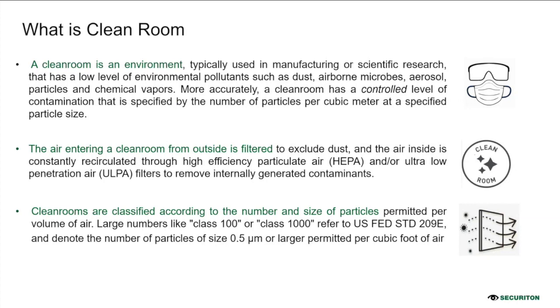So the question would be, how do you contain the air particulates? By using a filter, for sure. We will be using HEPA or ultra low penetration air, which is ULPA, filters to filter the air before it goes into the clean rooms.